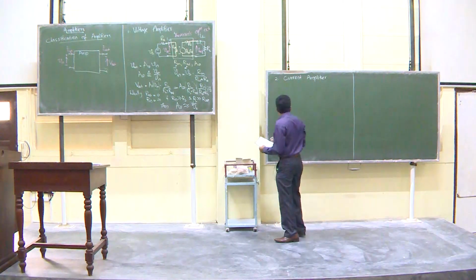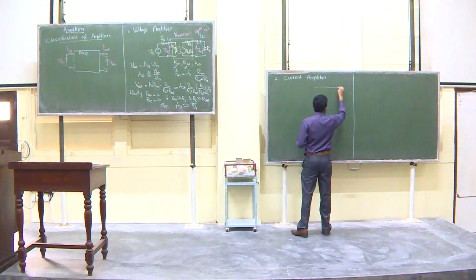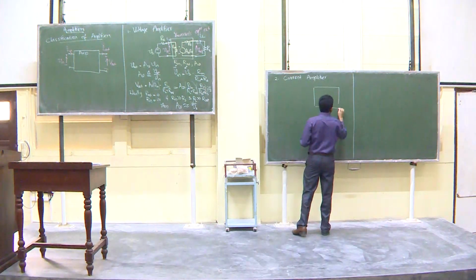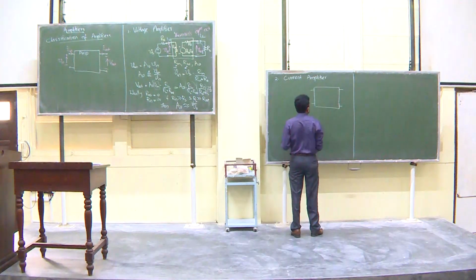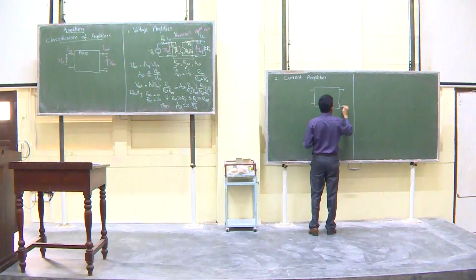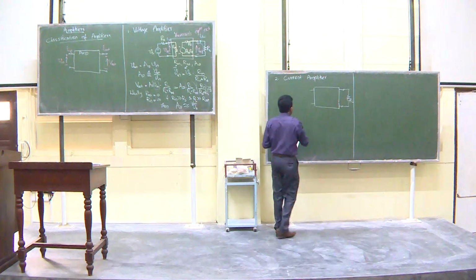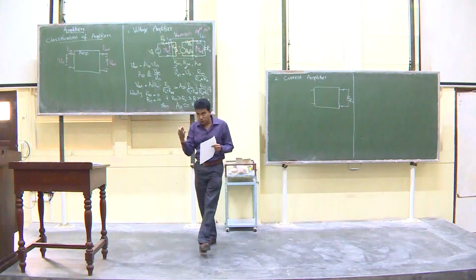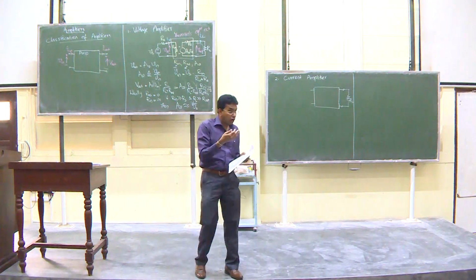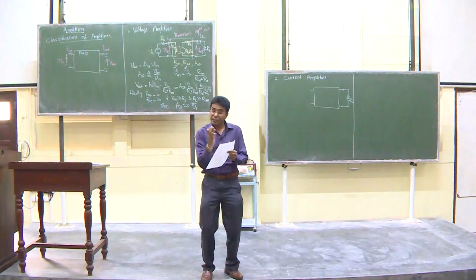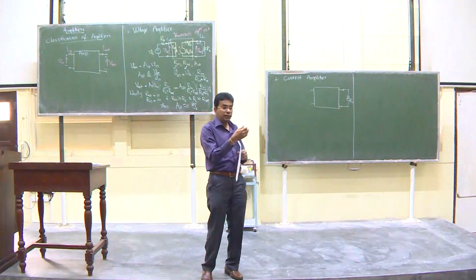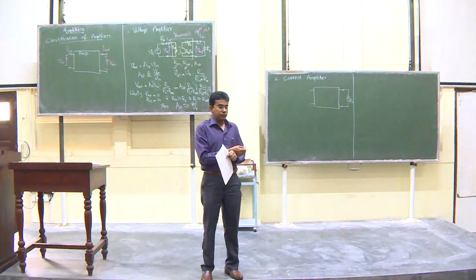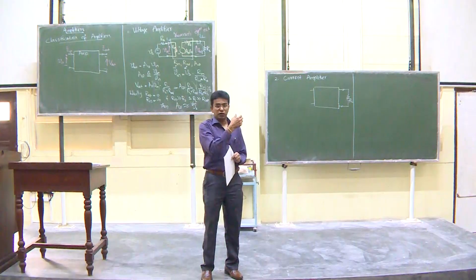If you draw the black box there, you have an input and output port, and I connect it to a load resistor RL. Now, my input is a current. So, it makes sense to model whatever is before this circuit as a Norton's equivalent circuit rather than a Thevenin's equivalent circuit, because what I control is the current, right.